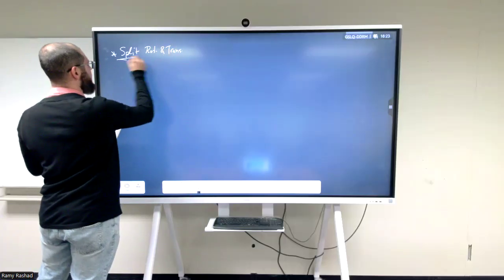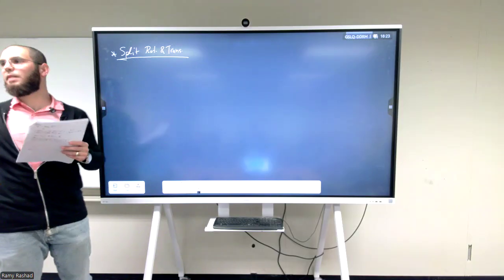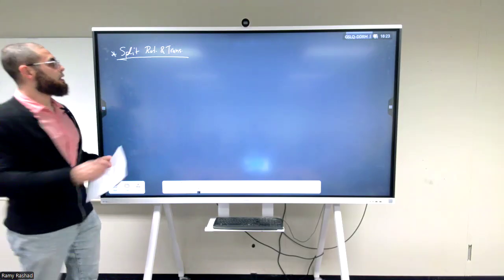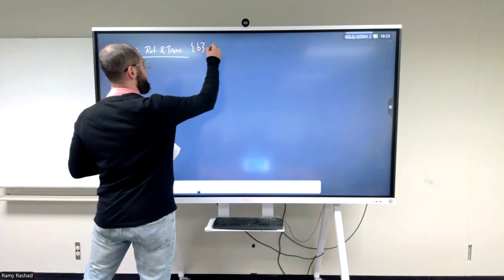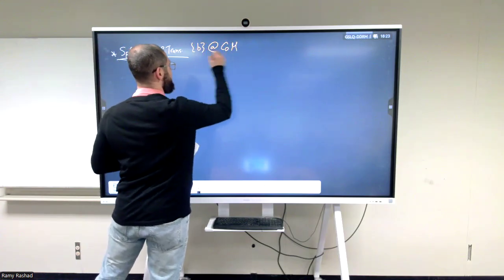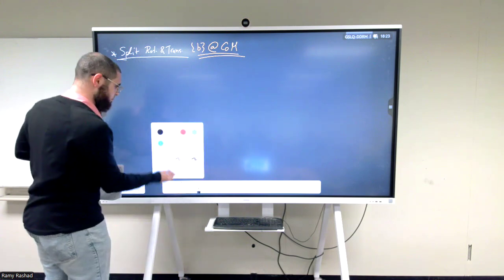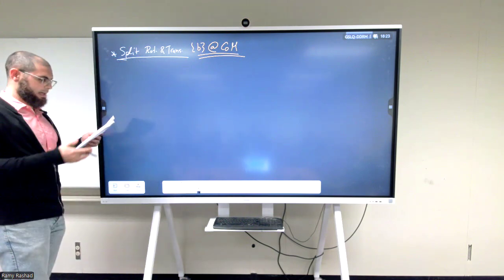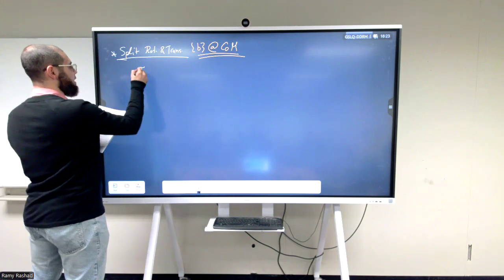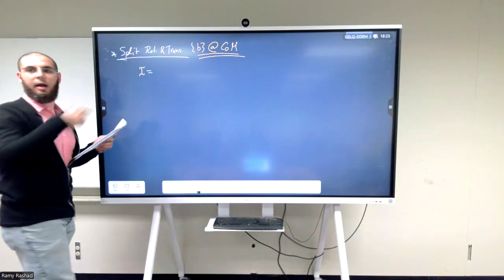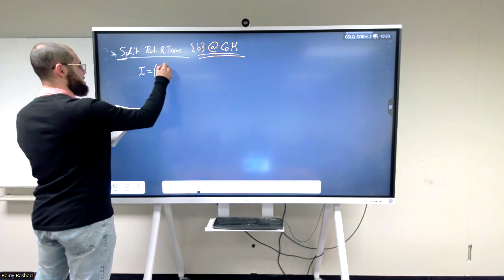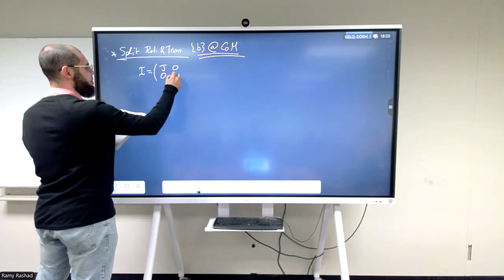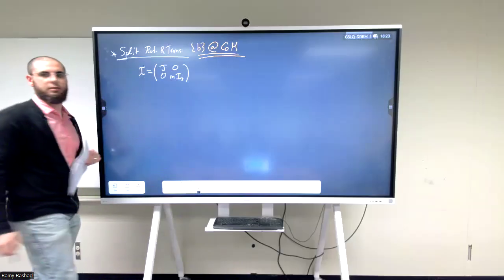But we're going to do this by making a very important assumption: that we're placing B at the center of mass. In that case, the inertia matrix, I'm going to drop the indices, you can fill them in later, will be just J, 0, 0, and M multiplied by the identity.